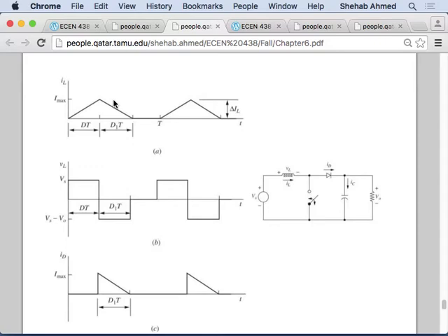Change the MOSFET's RDS on, see what happens, right? Maybe it's best to buy a MOSFET with a lower RDS on than to add a heatsink. I don't know, right? There are too many things interrelated to each other.